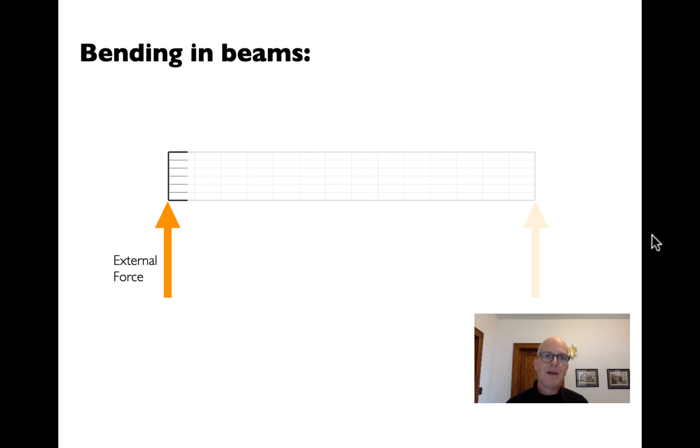What does that mean? Okay, let's take our infinitely small slice again on the left side of the beam. And when we were talking about shear, where we took that slice didn't really matter. We could take that slice anywhere before the next external force acting on the beam and be pretty confident that the shear in the beam would be equal and opposite to whatever the reaction was here. When we're thinking about bending, we need to think about where the reaction or where the load is in relation to the slice that we're taking.